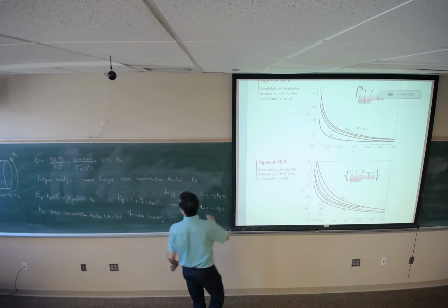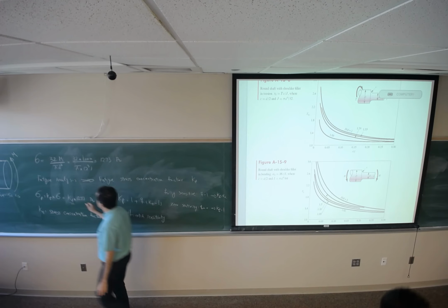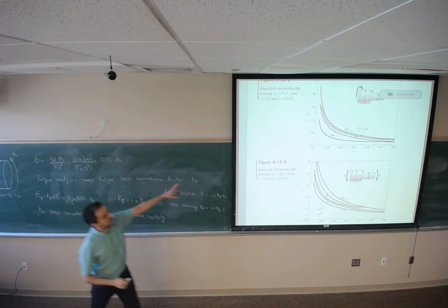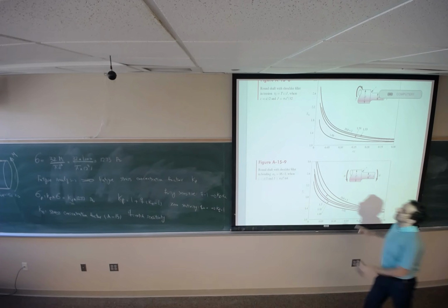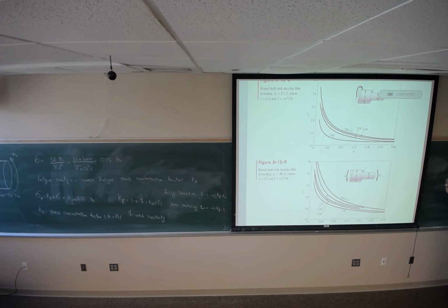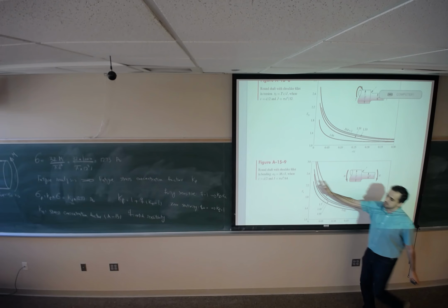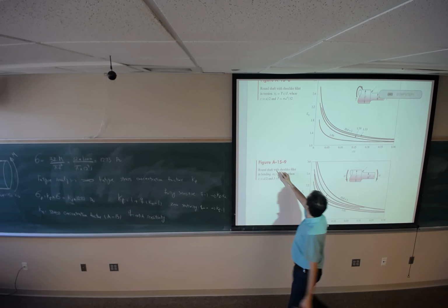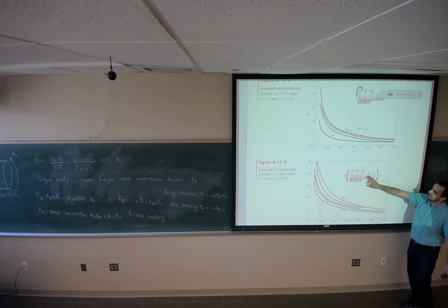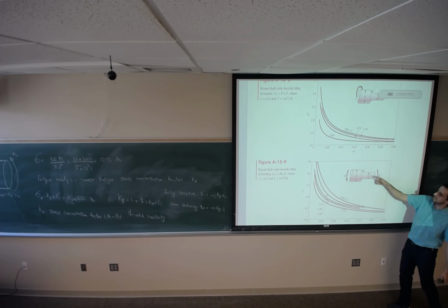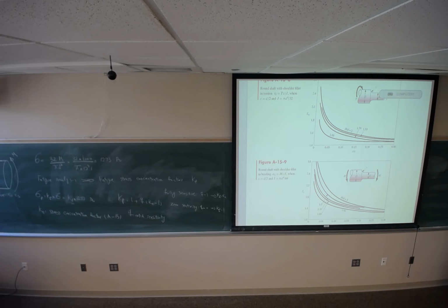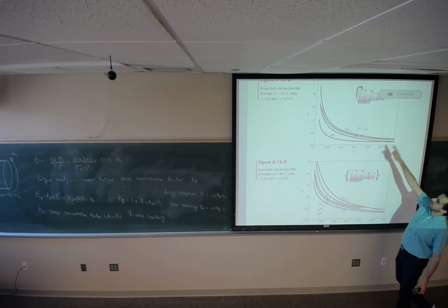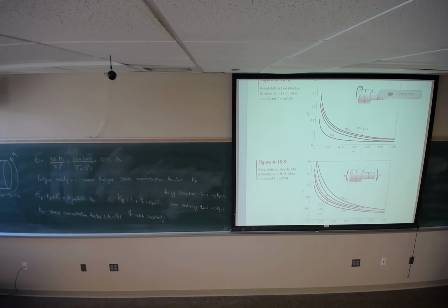So the first thing that I need to find is Kt. Look at table A15 on the back of the book and find the mechanical component and the loading which is similar to this one. Table A15-9 has this component with a circular cross section which is under pure bending moment. The other one is the same thing like this, but the load is going to be the torsion.